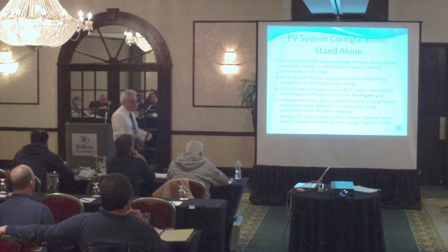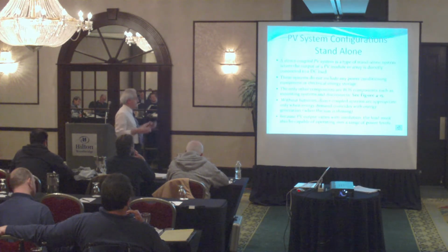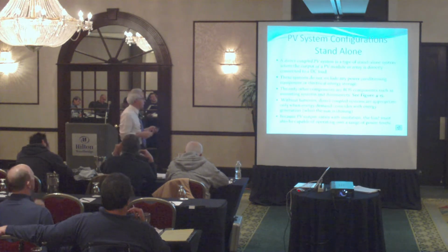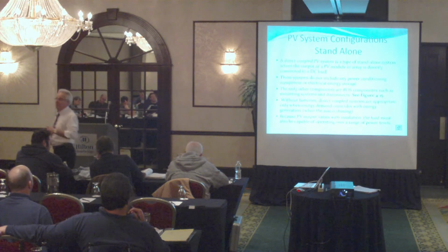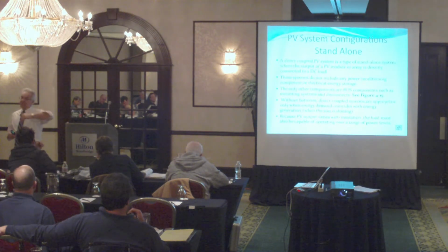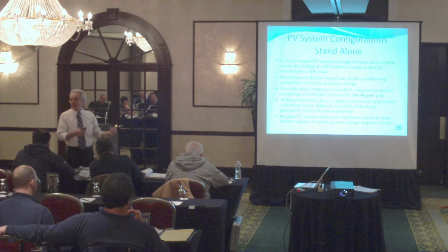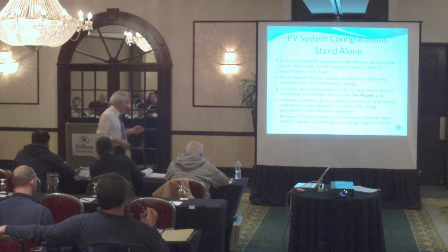With direct coupled systems you don't have any batteries. When the sun is shining, it produces energy and you supply the loads. The only problem is that you must precisely match your load to your system, and make sure you need your load to work when the sun is out. If you have no sun, there's nothing.